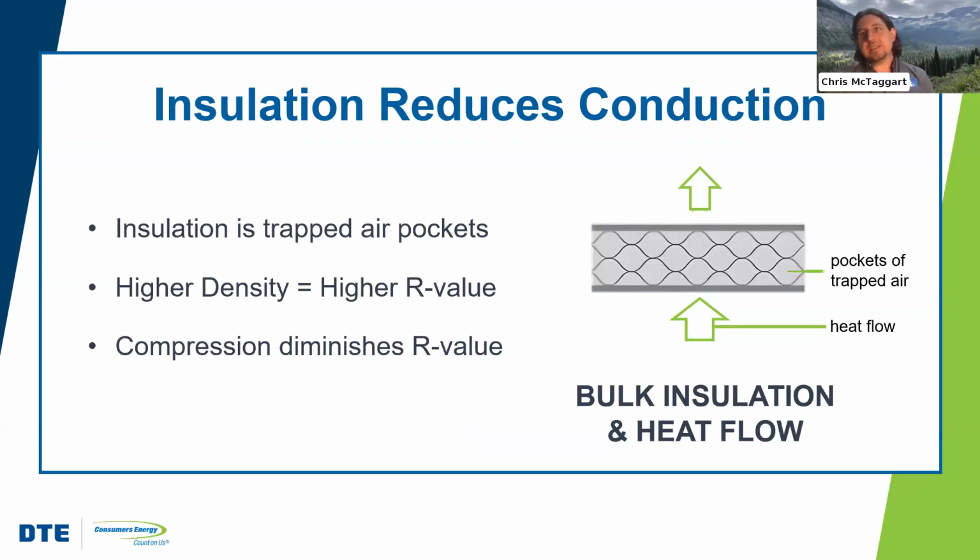So it's also interesting that the way that insulation works, it's counterintuitive. We're actually trapping air inside of an insulation product. And that's what ends up reducing the rate of heat transfer. So it's that trapped airspace inside of those insulation products that end up actually promoting greater R value and therefore less conductive heat loss, which is, again, very counterintuitive.